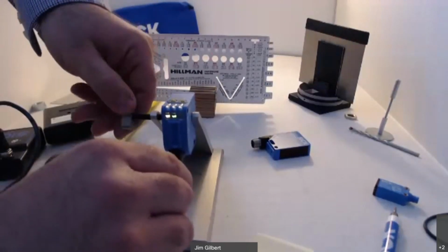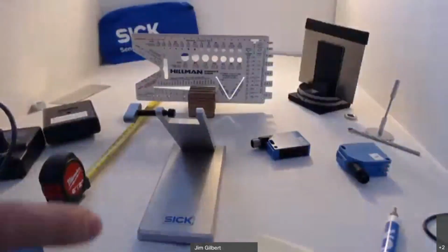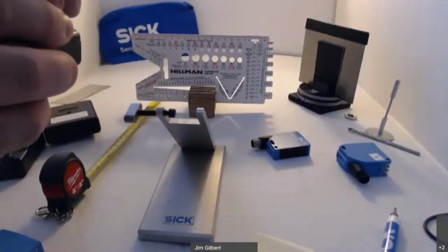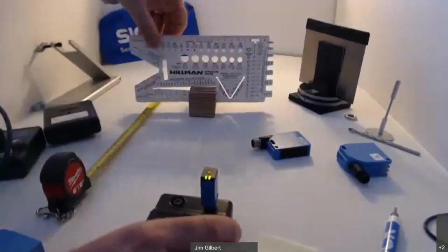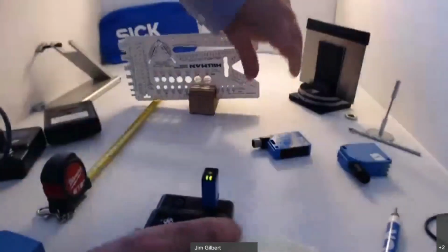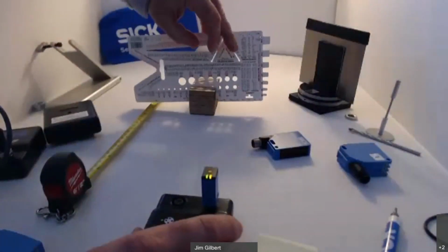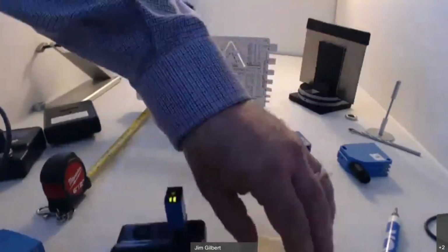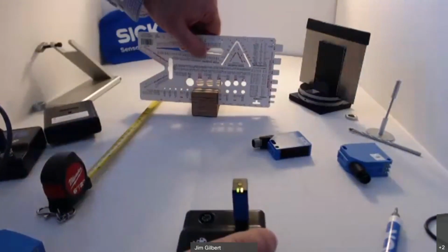We're going to take a look at another sensor, moving into the one we had mentioned before. This is the WTT4S. This sensor is very small, very compact. We're going to use the same drill gauge, except now I'm going to try to teach the sensor on the target directly behind one of these holes.